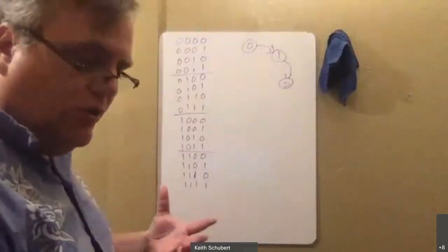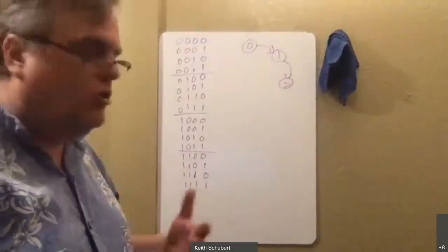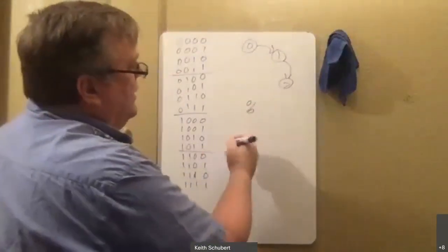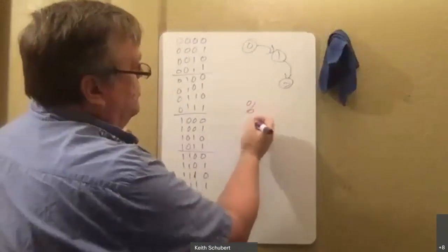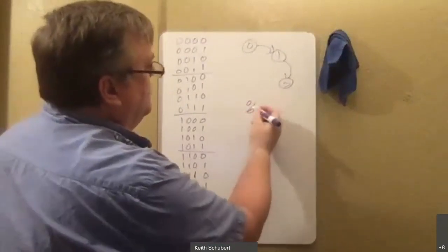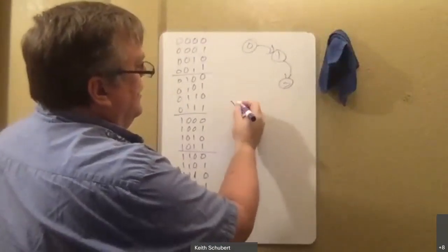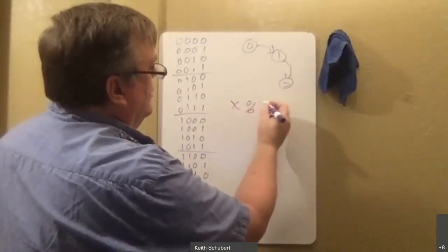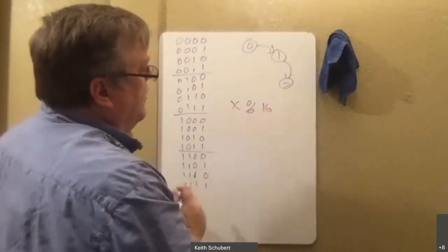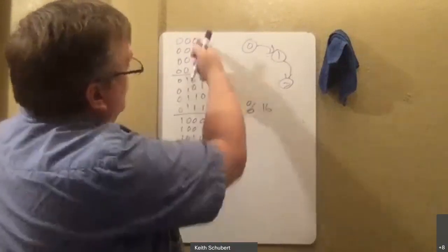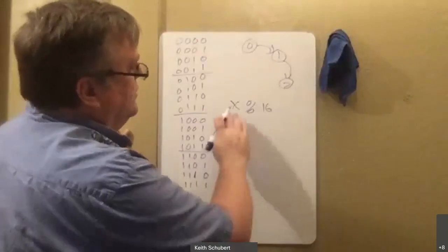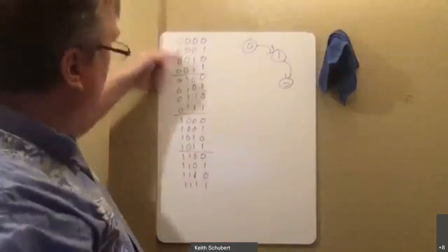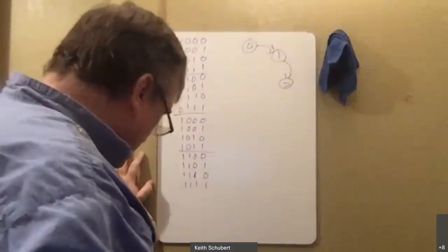And we will usually call these counters mod counters, we almost always do. Mod is your remainder. So classically we use percent as that symbol in C or C++. If we do some X mod some other number, whatever I want here, this one we're doing mod 16, it'll give me a result between 0 and 15. That's why we call them mod counters. And the number that it's mod is how many are in the sequence. All right.